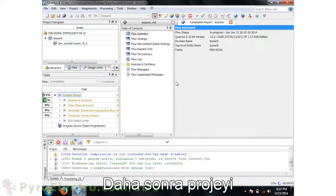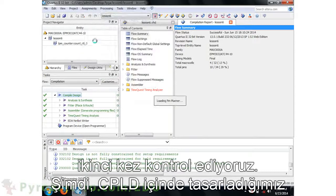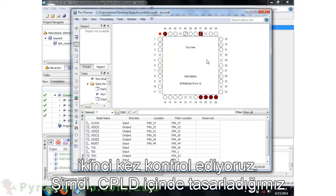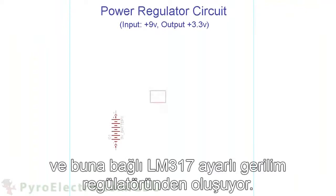Then recompile the project, and again, double check that the fitter and our defined pin locations match, as they do. Next, we need to build up the hardware schematic to go with the custom timer we just designed in a CPLD. The power regulator circuit is a 9-volt battery that connects to an LM317 variable voltage regulator.